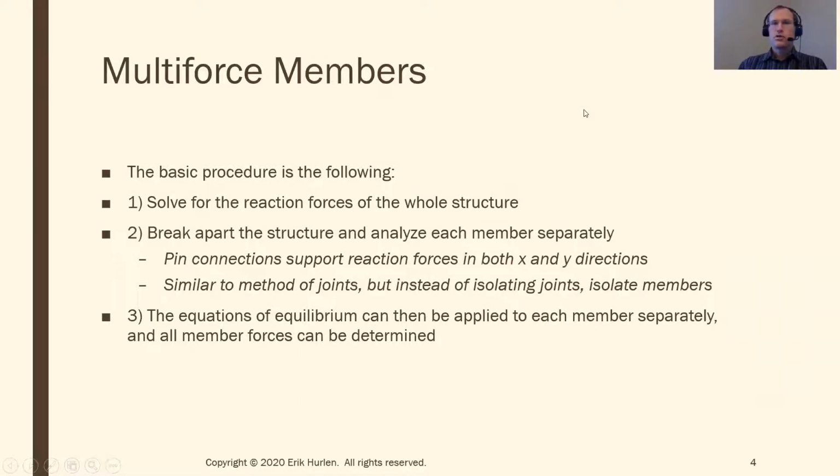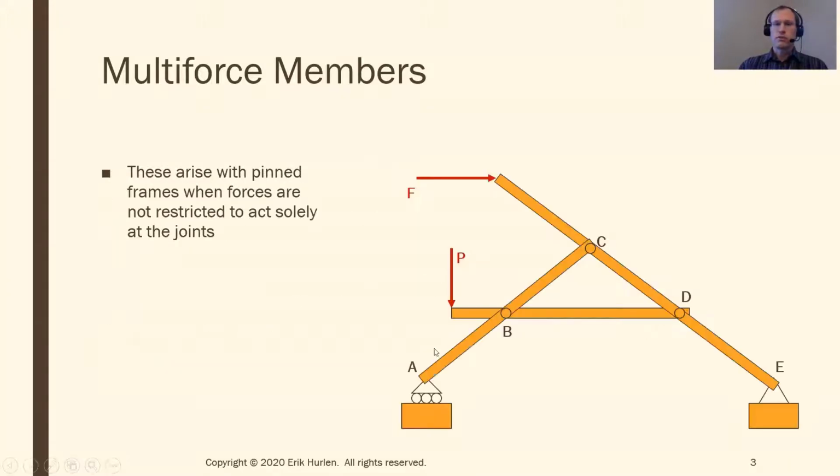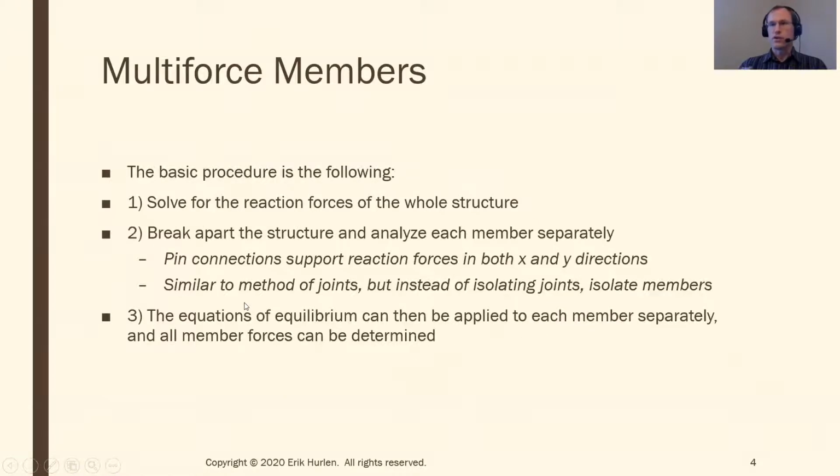So the basic procedure when dealing with multi-force members, the first thing to do is to solve for the reaction forces of the entire structure. So in the previous diagram, I had a roller connection at A, so I have some external force AY, and a pin connection at E, so I have some external forces EX and EY. Using the entire structure, I can solve for those reaction forces. So that's officially the first step.